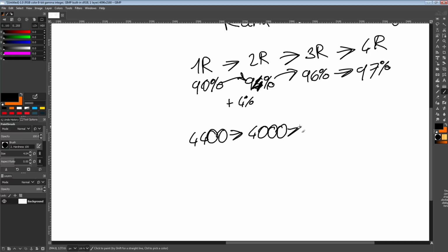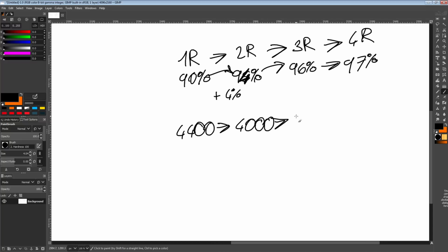Then you go to triple rank, and I've never run triple rank on Intel, so I actually have no idea what it does on Intel platforms. On AMD platforms, it actually works relatively okay, but you do lose like 100-ish megahertz compared to dual rank. So, yeah, I ultimately don't know what it does on Intel. Intel's memory controllers are kind of sensitive to doing weird things, so I'd expect it to probably end up at like 3733 or something. And then, of course, at the end of that, you've got like 3600.